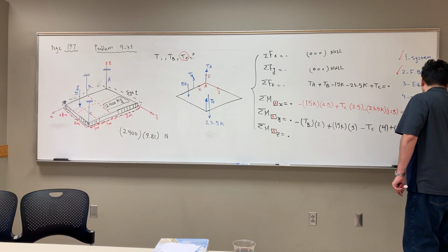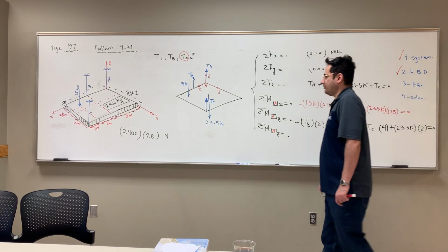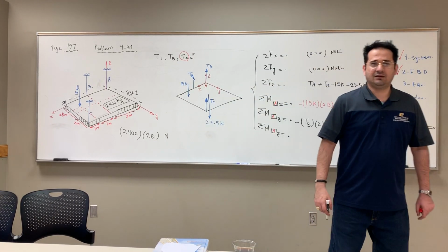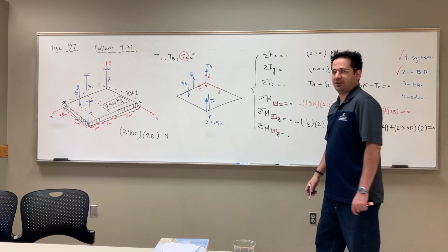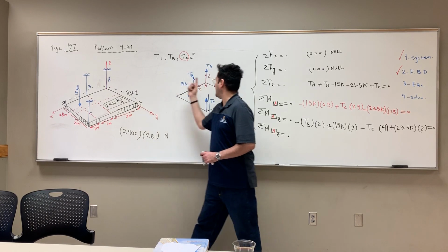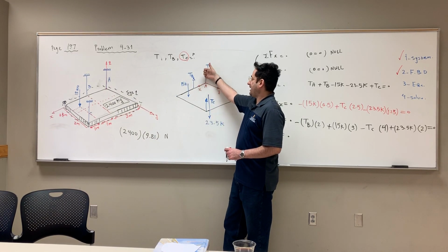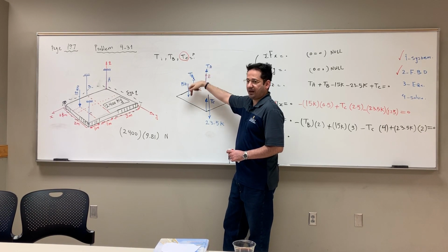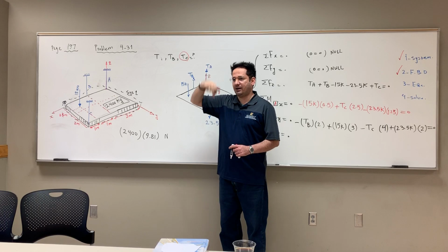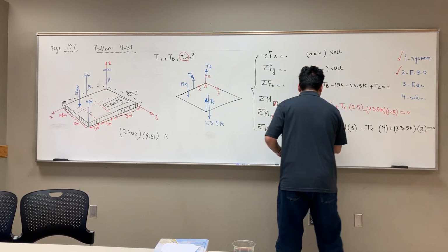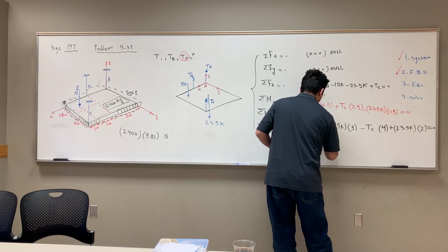Is equal to 0. Summation of moment about z-axis. No, 0, right? Nothing. You ask a question, well, this is my point A, and this is my axis. Which one creates a rotational effect like that? Nothing. You are all going parallel to the axis. If they are parallel, you just ignore them. So 0 is equal to 0, which is another null equation.